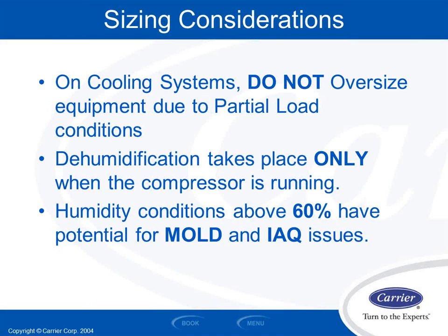Two-stage equipment is readily available in everything from the smallest residential to the largest commercial unit. There's no reason that 100% of the time you shouldn't be able to find a two-stage piece of equipment to do the job. Additionally, there's equipment with even more stages available, and you can get 3, 4, 5, 6, 8, 10 stages depending on what kind of equipment we're talking about. So the more stages, the better for dehumidification, because then I can put the exact amount of cooling on you need and get very, very long run cycles, which means I get excellent dehumidification.